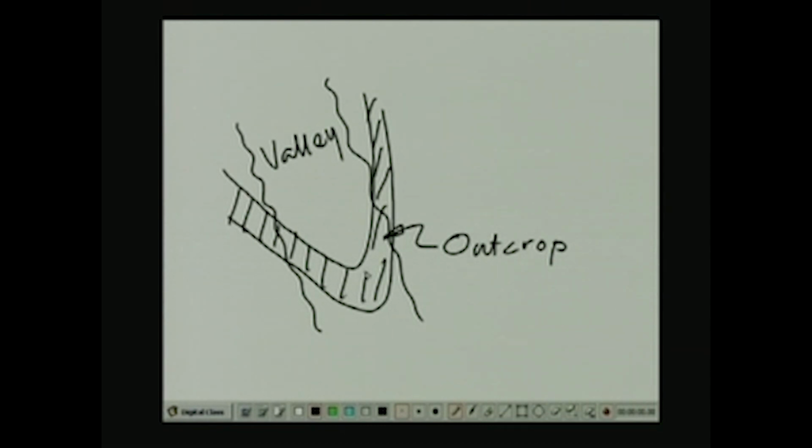at the point where the outcrop is at the lowest elevation, that is going to proceed in the down dip direction. So at this location the outcrop elevation is the lowest compared to the elevation of the outcrop at the flanks of the V shape. That is the reason why the tip of the V always points towards the down dip direction, irrespective of the surface topography within the valley.